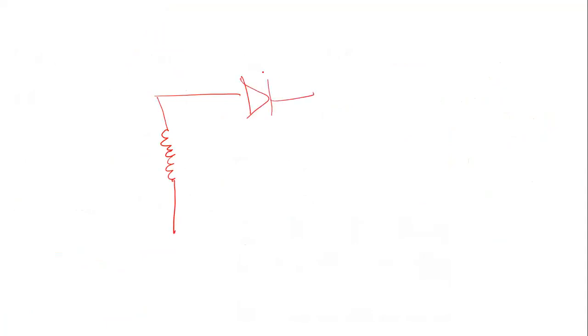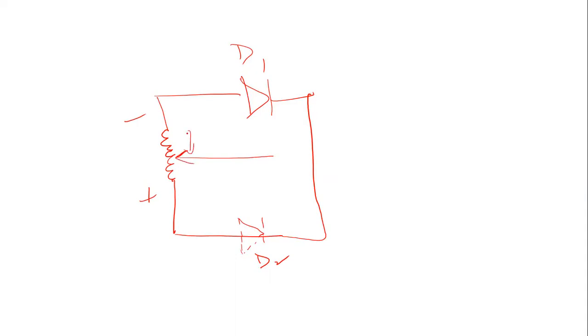Under reverse bias, you have diode D1, and diode D2 is conducting, meaning it will be totally passing through this good conductor. So you can assume that there is another diode, D2, but diode D2 is forward bias under negative cycle. If it is forward bias, then the current will pass through it. It will appear like a good conductor. So this is what we call a Vs signal, Vs equal to Vm sine omega t, and this is another Vs equal to Vm sine omega t.